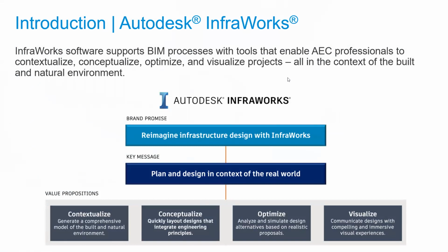Okay, I've just seen one question where someone is asking, why are you still using Bing images? This is not as dated as Google Earth. Bing just comes as a free imagery within Infraworks. It's meant to help you start the project, so you're not supposed to use it where you know that the project will go to the detailed design level. As a start, you can just start the project using those Bing images within Infraworks.